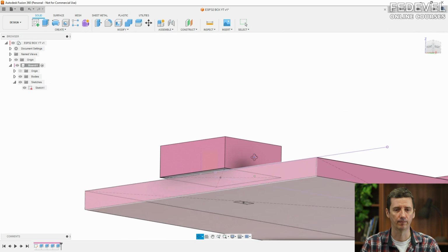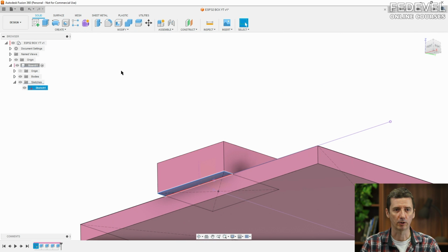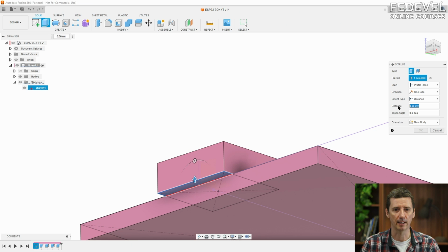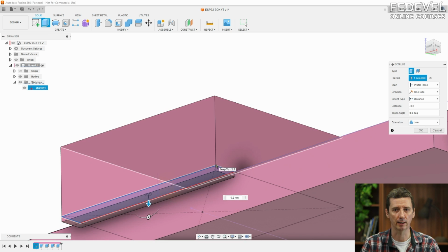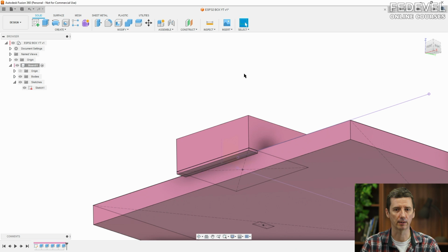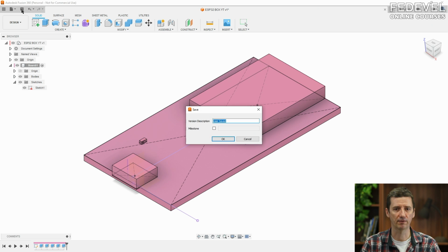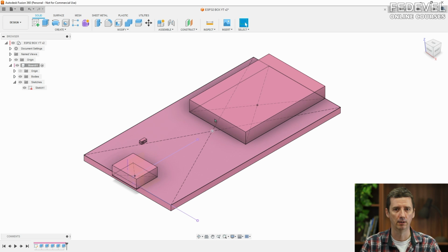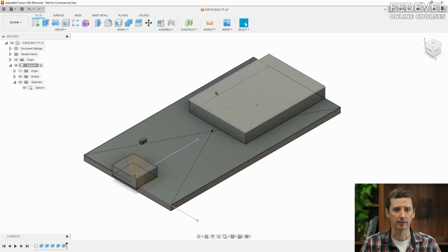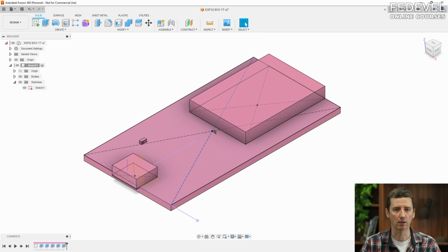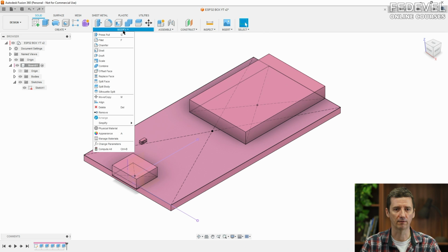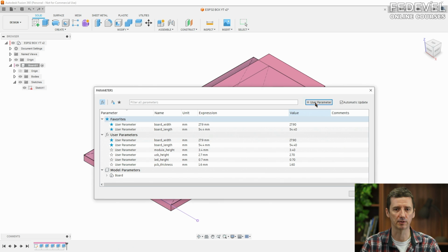Here specify height of the USB connector, and USB connector goes also a little bit down, so I'm going to put here like minus 0.2 millimeter, so it looks like real USB header or USB connector. Perfect. So this is very simple 3D model of our board. Save it. And if you see it like this, then go to inspect and use these colors. I always use it because you can very nicely see different components in your PCB.